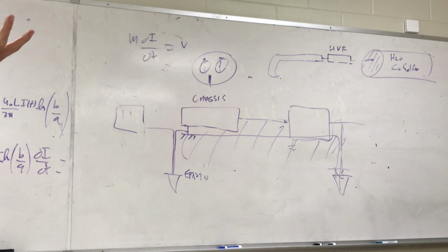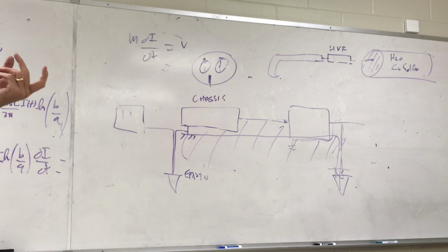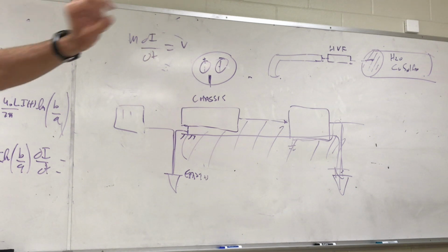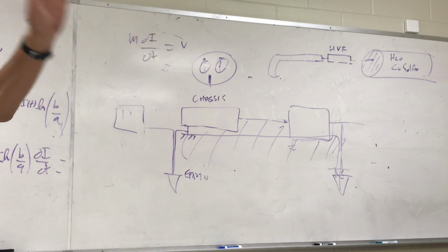Now, in the old days, they would have a fuse. You can't reset these. These are resettable. Anytime there's water in a bathroom or in a kitchen, or anytime there's water, all the outlets have to have a ground fault. They have to be on a breaker that's ground fault according to code.